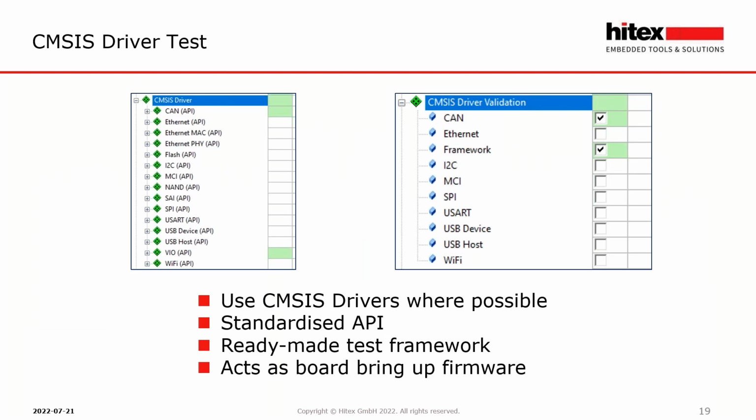Now, the driver layer, as I've said, will basically be the layer that talks to the underlying hardware. And ideally here, we want to use a standard driver layer. And the one that's ready to go is the CMSIS drivers. So these are standardized drivers that talk to a wide range of common peripherals on a lot of microcontrollers.